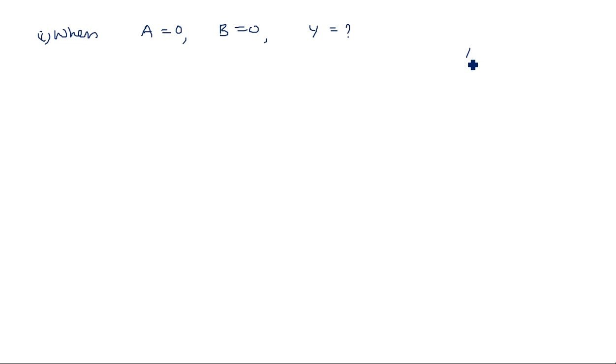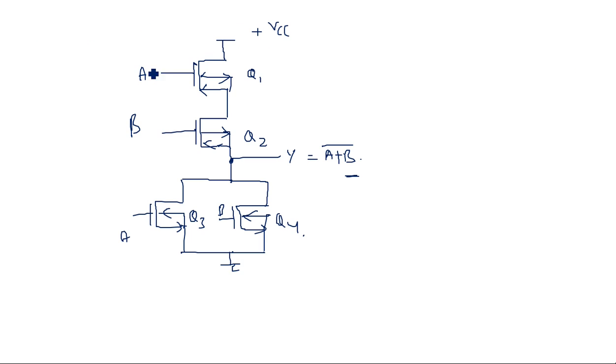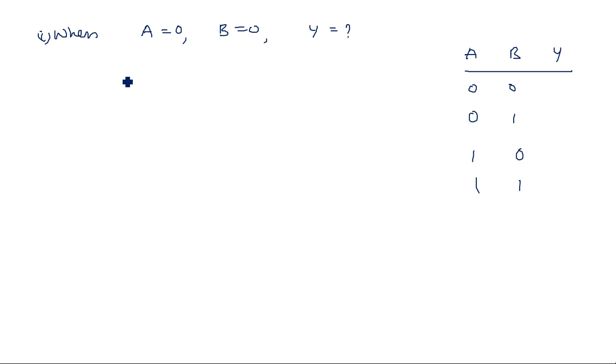Based on the truth table, let us take the truth table and we are checking now whether it is satisfied or not. So 0 0, 0 1, 1 0, 1 1. So 0 0 means A is equal to 0, B equal to 0, that makes the PMOS transistors on and NMOS transistors must be off. So this makes PMOS on, NMOS off for 0 input, because PMOS is connected in the reverse direction compared to NMOS.